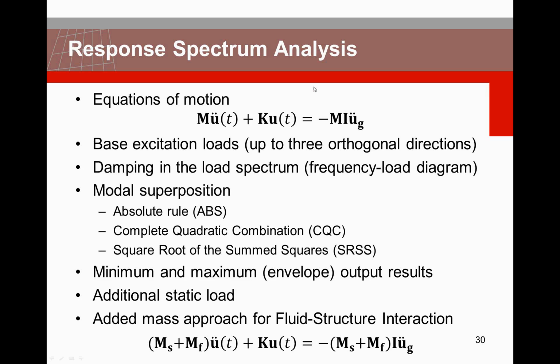The next step, which also makes use of these eigenfrequencies, is a response spectrum analysis, or RSA. The equation of motion here is your mass times your acceleration plus your stiffness times your displacement, which equals minus your mass matrix times your ground motion.